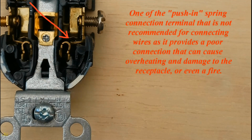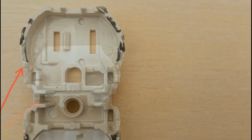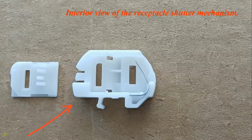One of the push-in spring connection terminals that is not recommended for connecting wires, as it provides a poor connection that can cause overheating and damage to the receptacle, or even a fire. Tamper-resistant receptacle shutter mechanism inserted into the front part of the receptacle. Shutter mechanism removed from the receptacle front base.